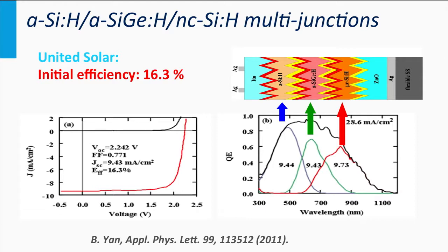Wavelengths at 550 nanometers are utilized by the top cell and middle cell. Wavelengths at 650 nanometers are utilized by all three junctions. Wavelengths above 900 nanometers are only utilized by the bottom cell. Consequently, optimizing thin film silicon multi-junction solar cells is a complex interplay between the various thicknesses and light trapping concepts used in the solar cell.